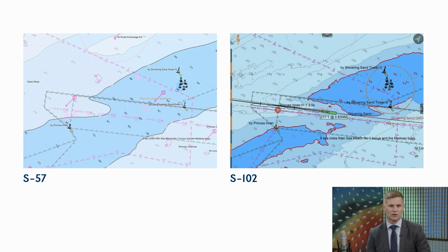In the ECDIS screenshot showing the S-57 ENC, you can see the large area that looks out of bounds because it's bounded by the black safety contour. What this means is effectively, even though that vessel's put in its 7-meter safety contour, there isn't any 7-meter safety contour in the S-57 data. So it defaults to the safest contour that's available, and that happens to be the 10-meter contour. So according to the ECDIS, you cannot navigate through there safely.